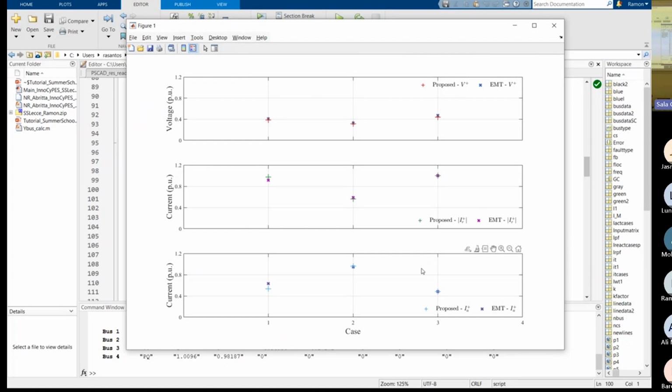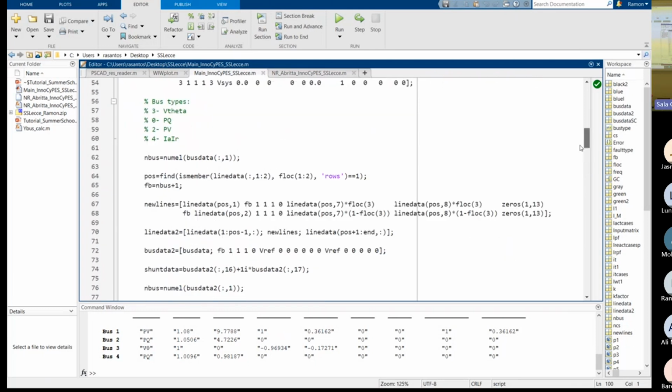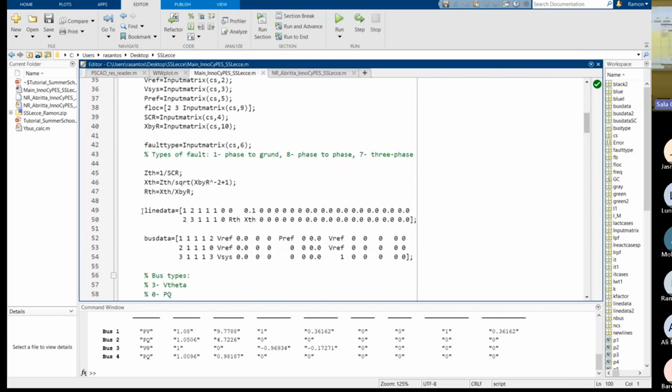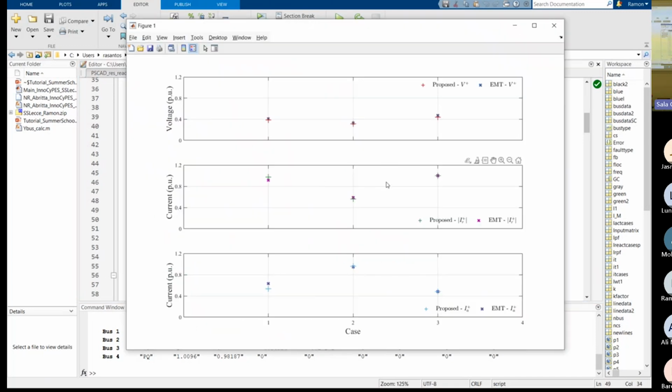And the result usually is much better, actually, because here there is this piece, these lines here, they are representing the system, and I am completely neglecting the filter of the wind turbine, and also I'm approximating the impedance of the transformer of the wind turbine by 0.1 pu reactive. This is because the actual values are protected by intellectual property of Siemens Gamesa, and I cannot just show it here. So if we had the actual values, this would be pretty much a perfect match in these estimations.